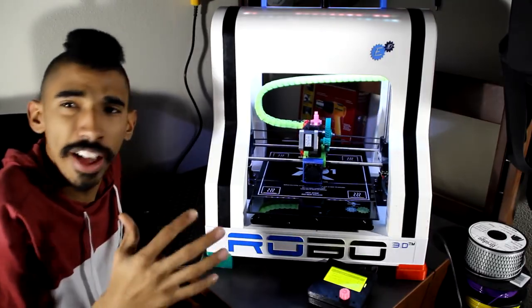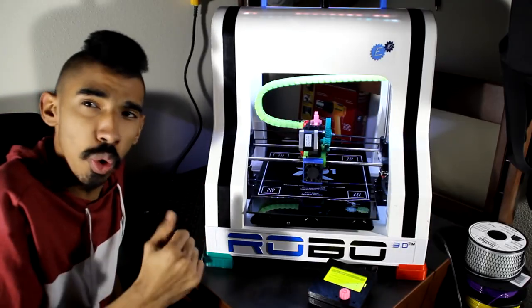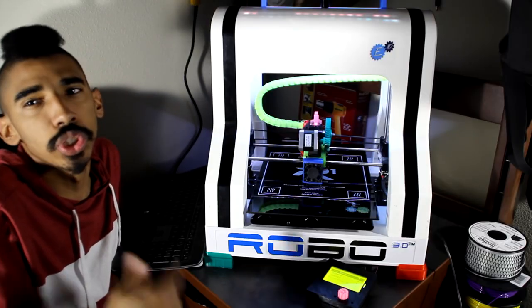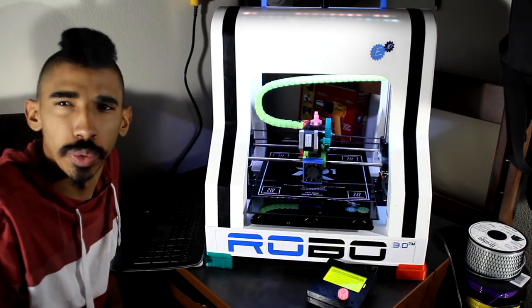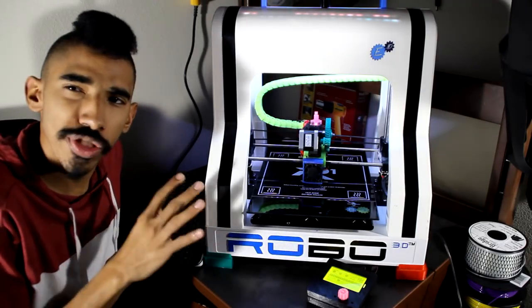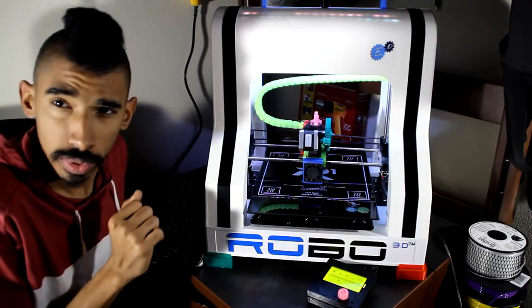It's like an M25 mixed with a G1 and a few other things. So it's really cool, but you need an LCD controller to do it. If you don't have the LCD controller, it doesn't actually work, so be careful with this one. And we're gonna have a more detailed video later on exactly everything you can do with that M600 command. So stay tuned for that.